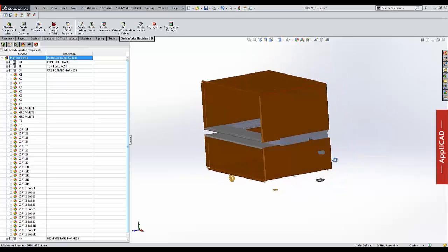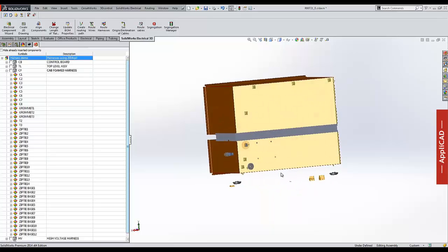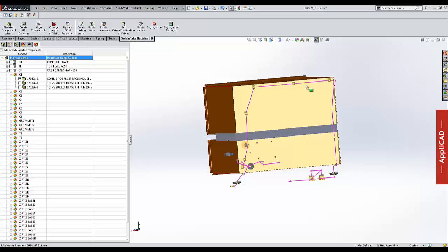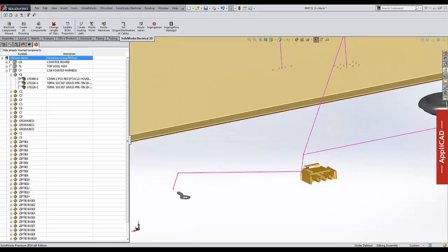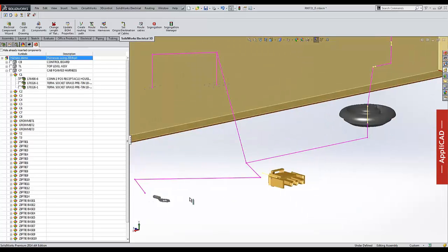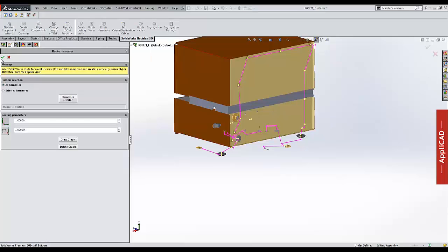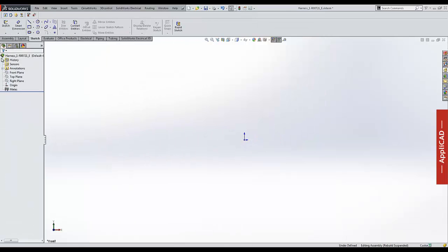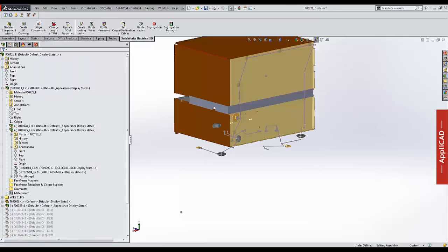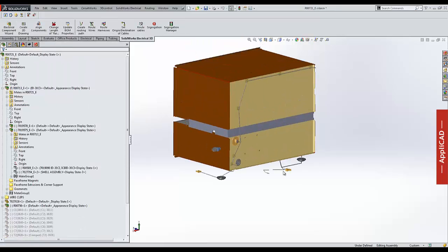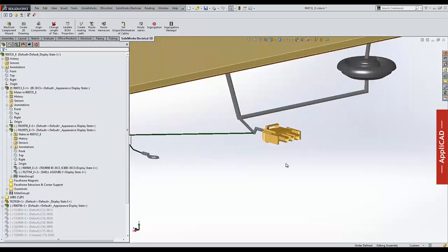So this, as you may have guessed, is a freezer. And the harness is going to run around the back. I had already placed all of my mechanical parts, and had gone in and predefined a sketch where these are all going to route to. And these are just guidelines to tell it where it's going to go. As you can see, not everything is fully connected. Doesn't need to be. Just go ahead and tell it the route. And that's it. The harness has been routed.